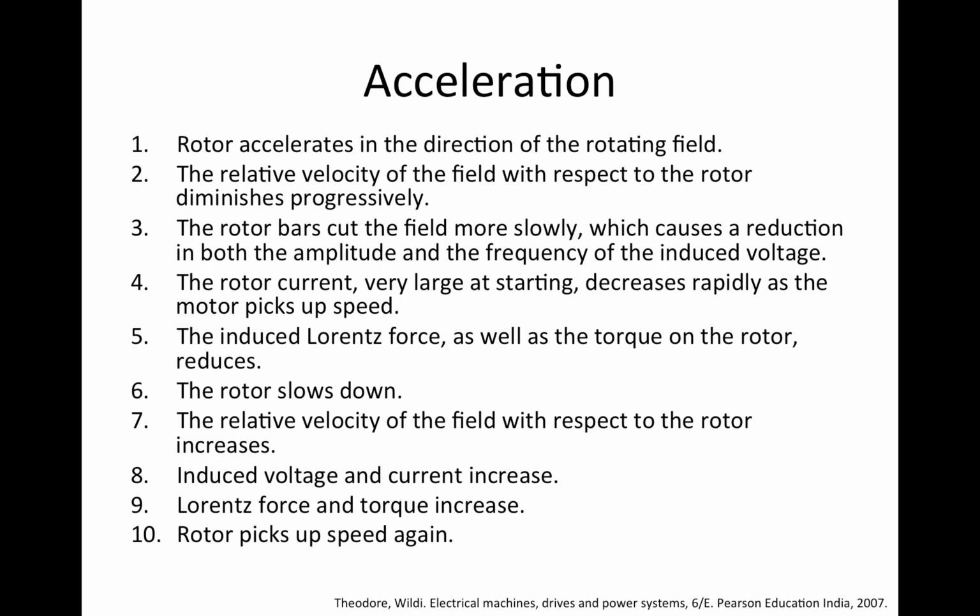So remember that the rotational speed of the magnetic field created by the stator is fixed at the synchronous speed. As long as the frequency of the alternating current is not changing and the number of poles per phase is not changing, the synchronous speed is fixed. So the rotational speed of the magnetic field inside the stator is constant.